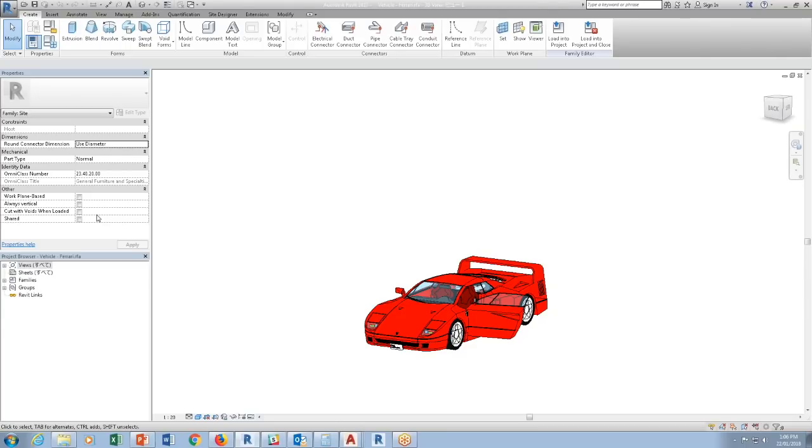All right. So any questions so far? Yeah, I learned this in about 2012, and then I think it was at Autodesk University, there's a guy named Marcelo who showed there are 5 ways of doing scaling inside Revit. So this is just one of the ways. This is the simplest. The other one requires you to look at adaptive components, which is way trickier than people need to do. But this one is the easiest because you can just dump whatever inside the planting and then say scale, and there we go.